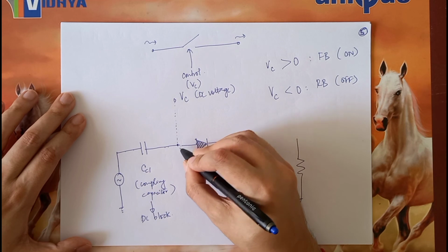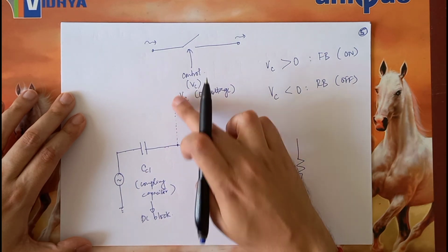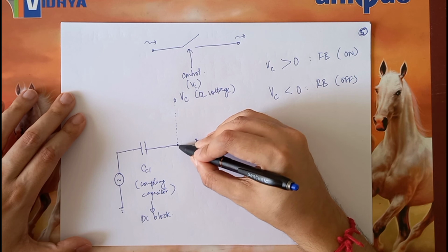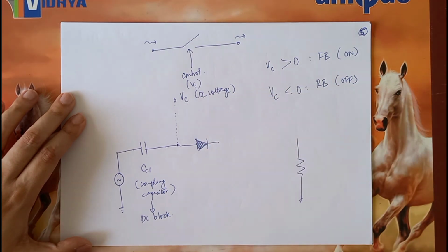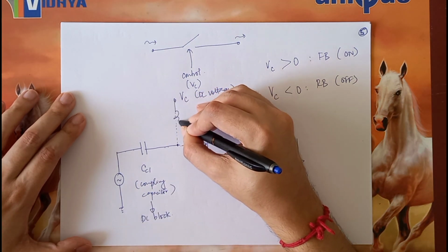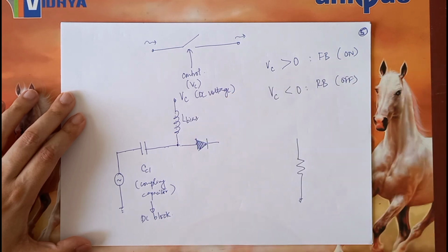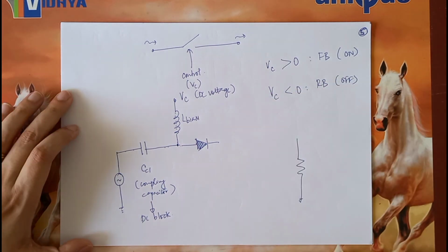We again have the AC signal over here and a DC point over here, which will again cause the anomaly. So therefore, these two points need to be isolated in such a way that now this DC can come here, but the AC cannot reach over here. So what we can do, we can use an inductor over here. Let's call this L bias 1.